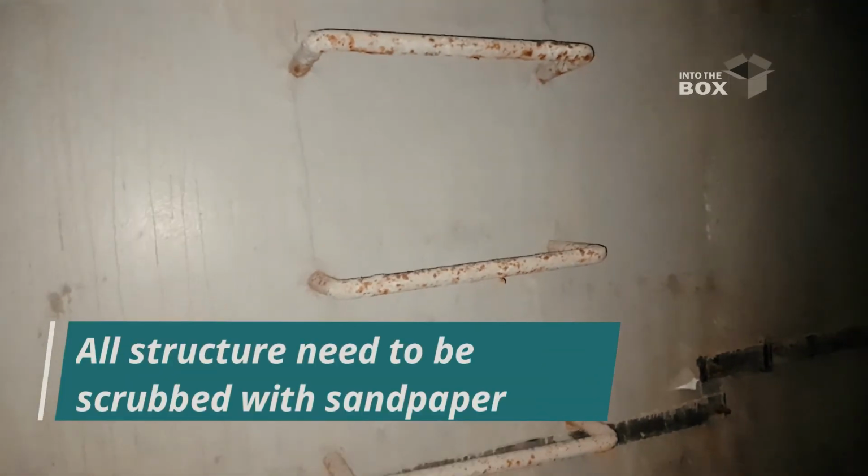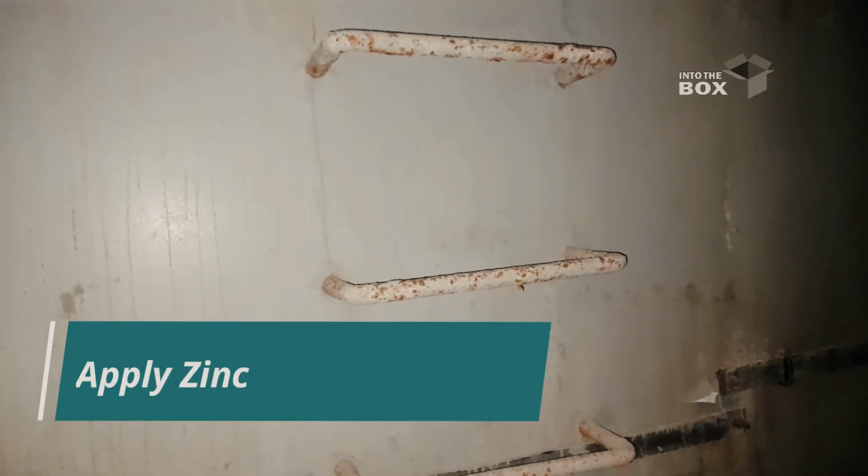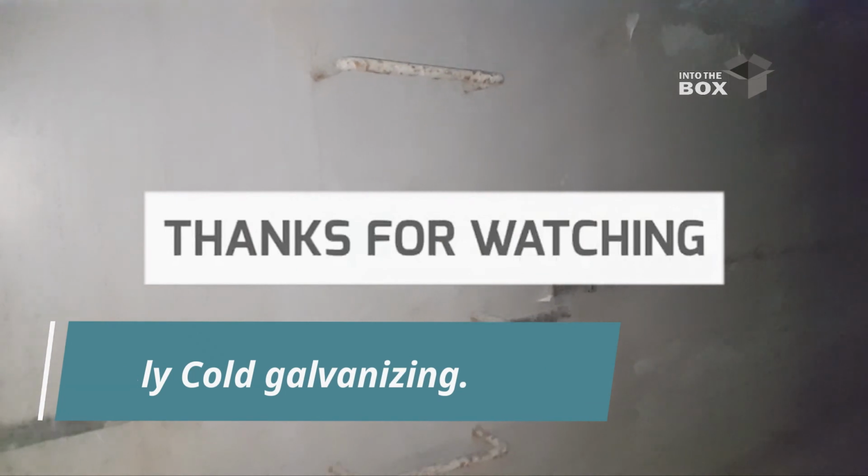So in order to protect it, first of all we need to grind it, and later on we should apply zinc-rich coatings over it in order to protect it against the harmful effects of the environment.